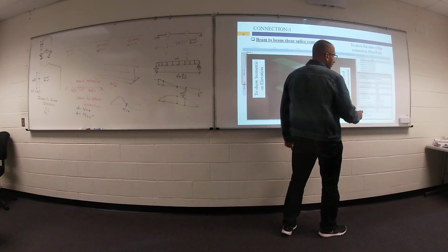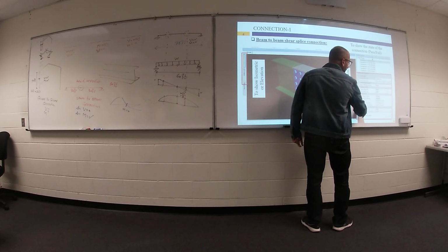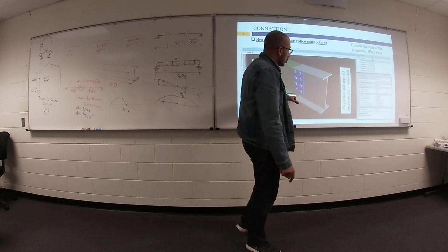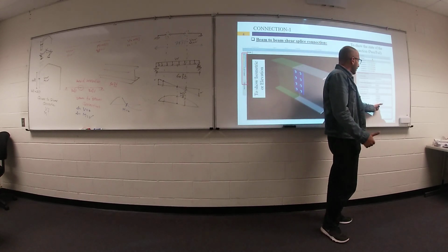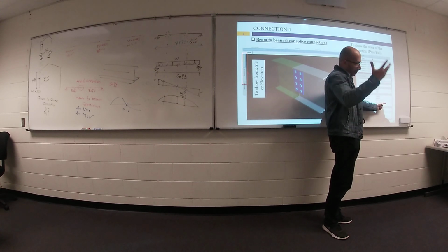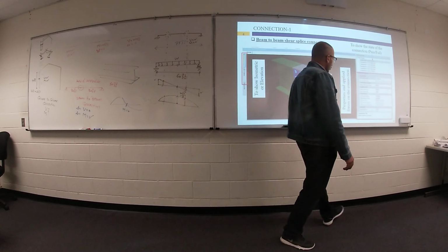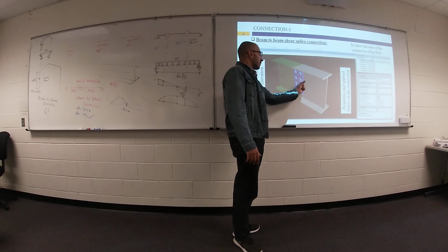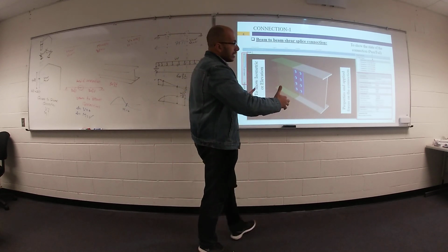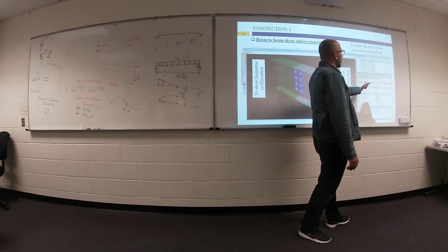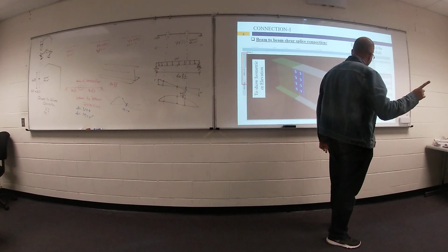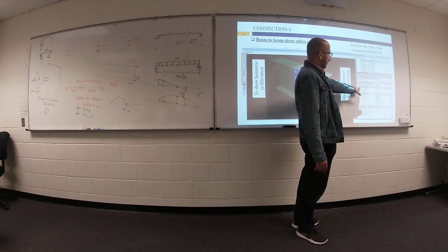Also, you can figure out the left beam bolts. What are the bolts here? You can figure out the diameter of your bolt, the type of bolt, the group, and also you can figure out the properties for the right bolts and the number also. You can try until the program tells you whether this connection is safe. One more thing, yeah, loading.